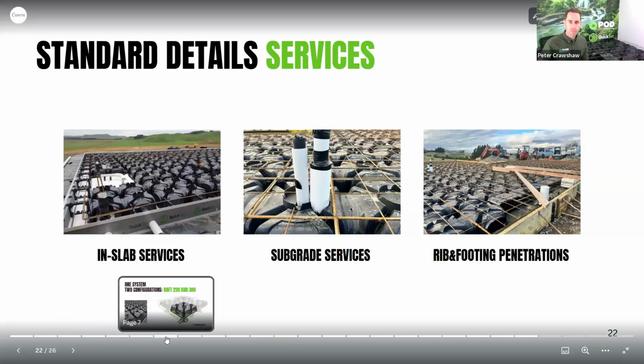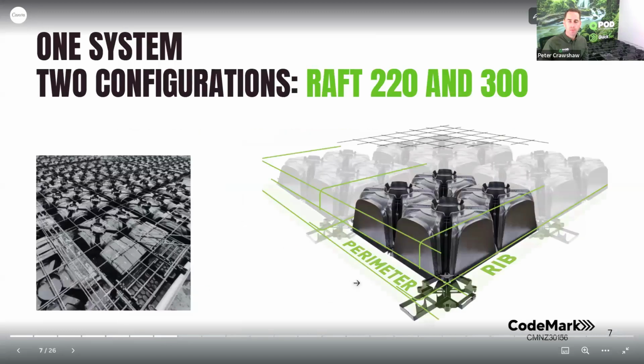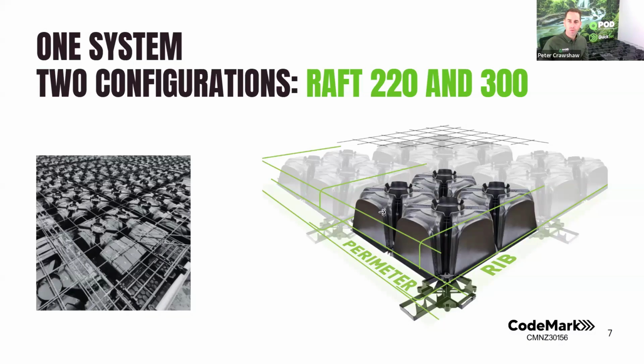What they're filled with, I'll just jump back to the slide here because this pictures the pod quite well. So this is a recycled plastic pod joined as a group of 4, and then inside here is an encapsulated pocket of air. I've got them right behind me here. They've got to be built structurally so contractors can clamber all over them. You can really jump up and down and they're not going to go anywhere. So that's a hollow void of air, but it's all structurally strengthened by that shape of ribs and ribbing.